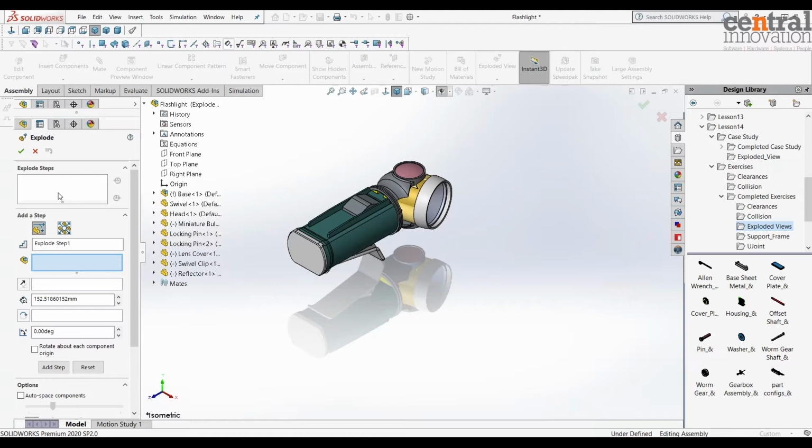So when we have another purpose, and for any reason we want to use the animated exploded view for other purposes, maybe such as marketing or any other reason, in that case, the order of the exploding of the components matters. So if for any reason you didn't follow your order, you can reorder your steps. We will go through them later on when we create some steps. Here it keeps a record of your exploded steps.